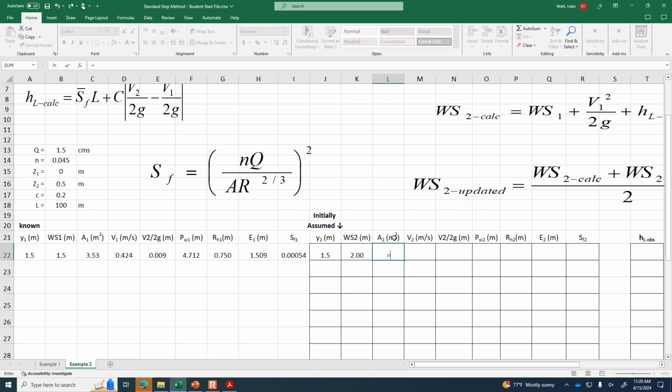And then the wetted perimeter is going to be this side piece here. So the wetted perimeter is the square root of y squared plus y squared, because if it's 2y total across the top, then that means it's y here and y there. So it's just the square root of y squared plus y squared. So that is the square root of 2y squared.